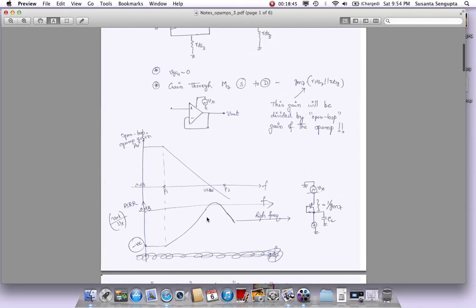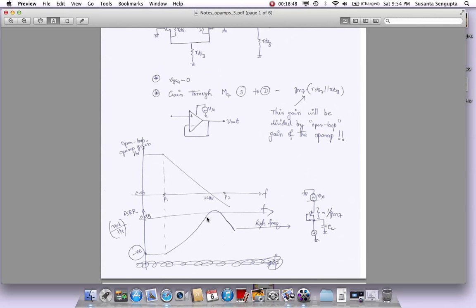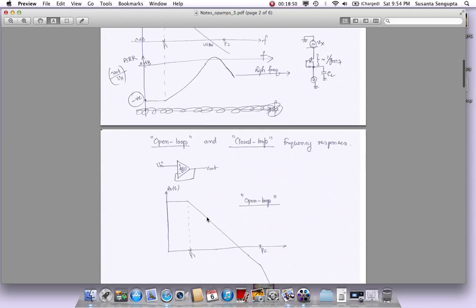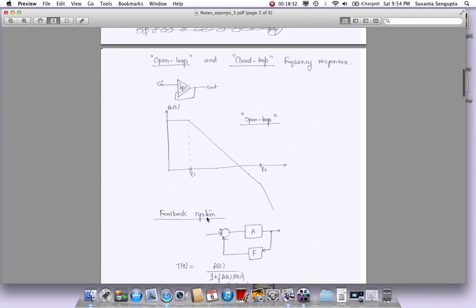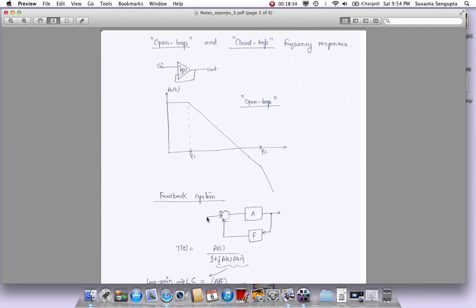So hopefully now this gives you some idea about the power supply rejection. After this, I think we have covered most of the stuff with op-amps in terms of common mode rejection, power supply rejection, noise, offset voltage, and all that stuff. Something I have experienced myself over years is that we design an op-amp and only focus on its open loop characteristic, but it's not just open loop that matters at the end, because the op-amp is always going to be put in a feedback system.